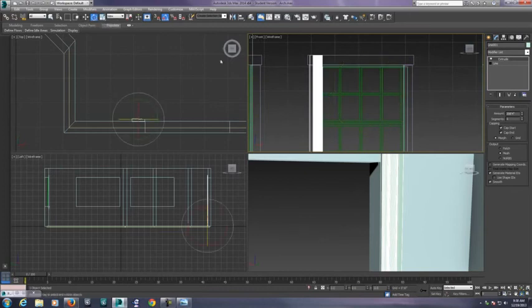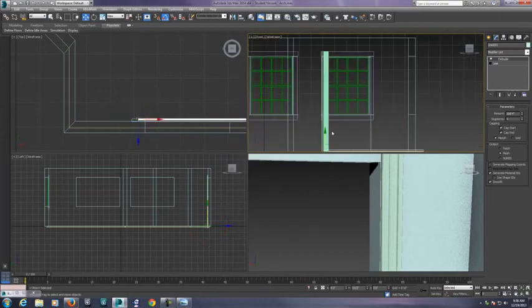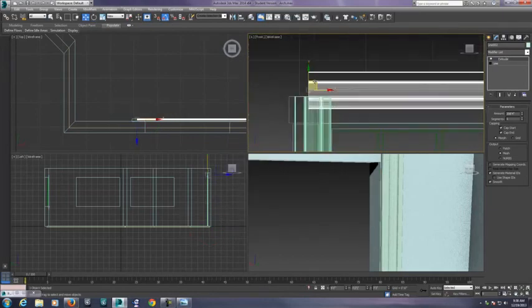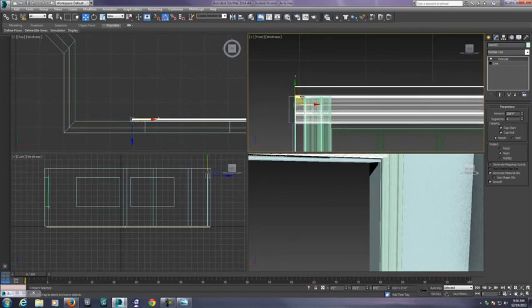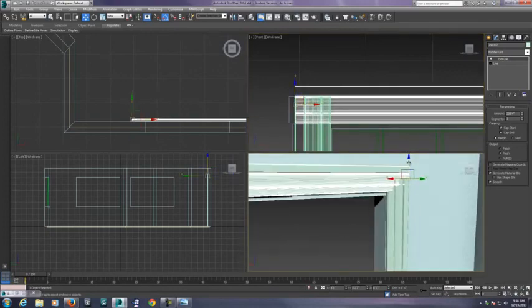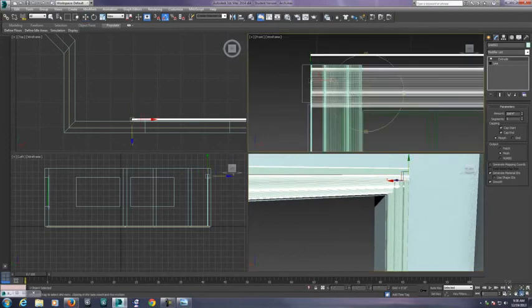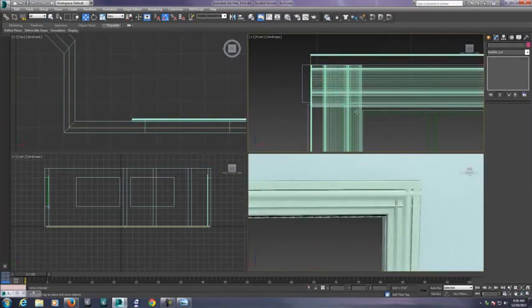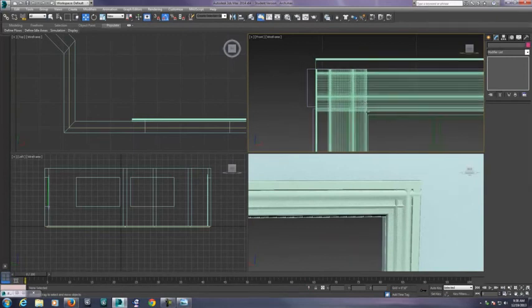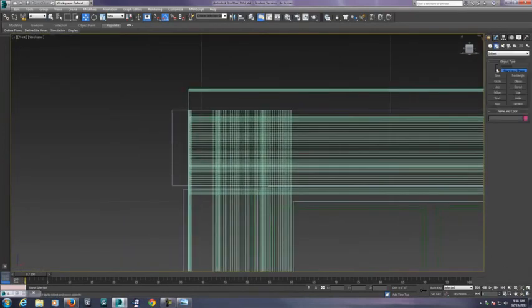So once you're done with one piece, it's just a matter of cloning that piece out and placing it along the door frame like we did in the earlier section here. All right, maybe I have to extend it a little bit more. There's my door. I can bring that down just a little bit. And you'll notice that they overlap here and they collide. And when you work with real architectural trim, what you do is cut that or miter it, as they call it. One form of mitering here is to go out and create a line.